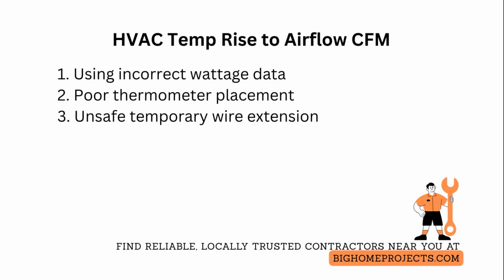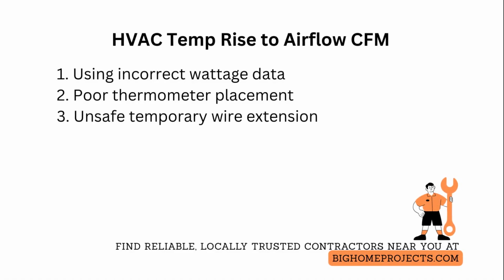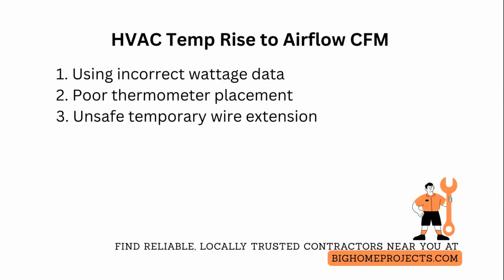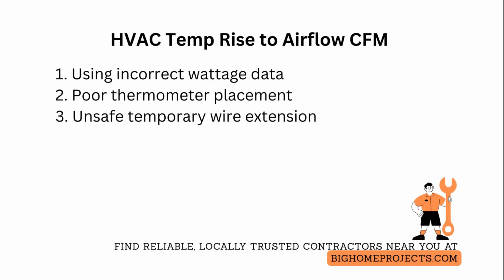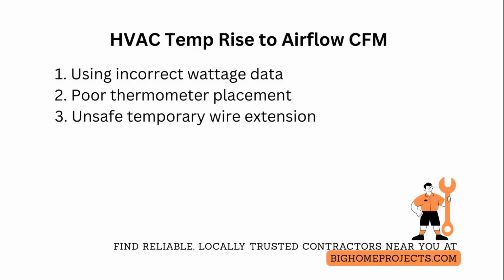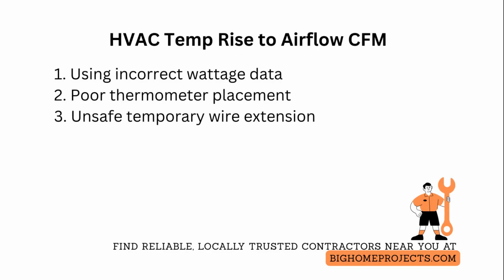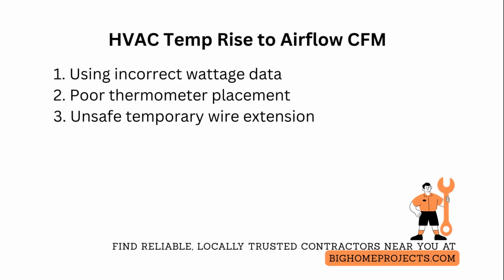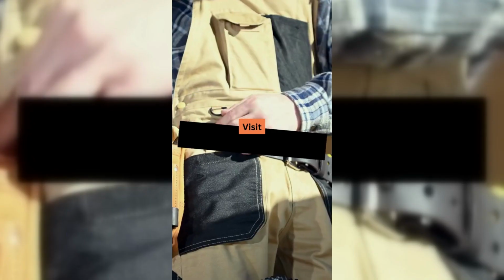One of the frequent errors is unsafe or improper extension of the heater's supply conductor while trying to access for amperage measurement. Fix this by de-energizing the circuit, using a properly rated splice kit with a temporary larger gauge extension only long enough for the test, retorquing the original connection to the manufacturer's spec afterwards, and restoring all covers and insulation per local electrical code.